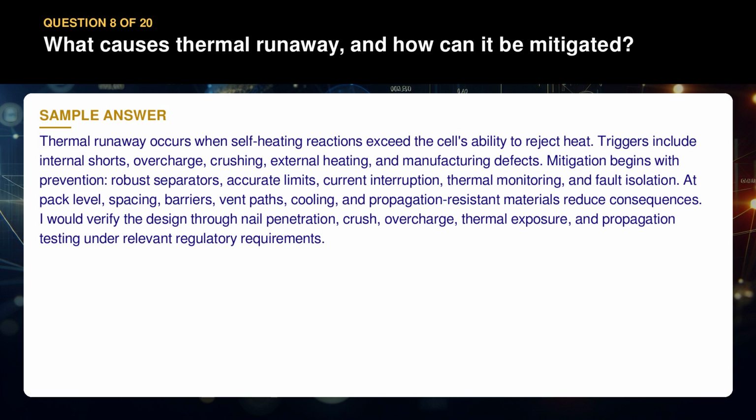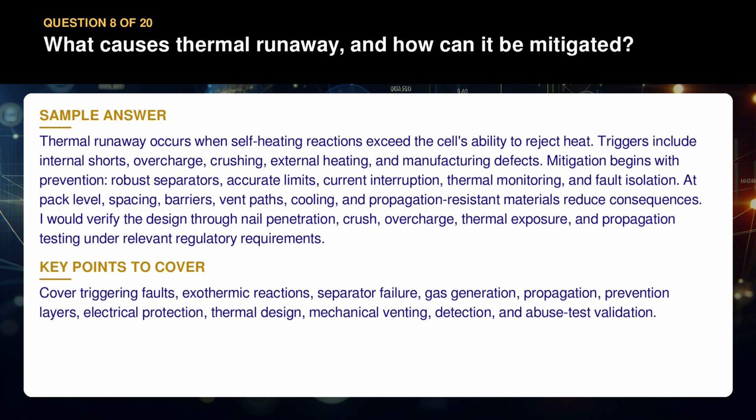I would verify the design through nail penetration, crush, overcharge, thermal exposure, and propagation testing under relevant regulatory requirements. Cover triggering faults, exothermic reactions, separator failure, gas generation, propagation, prevention layers, electrical protection, thermal design, mechanical venting, detection, and abuse test validation.